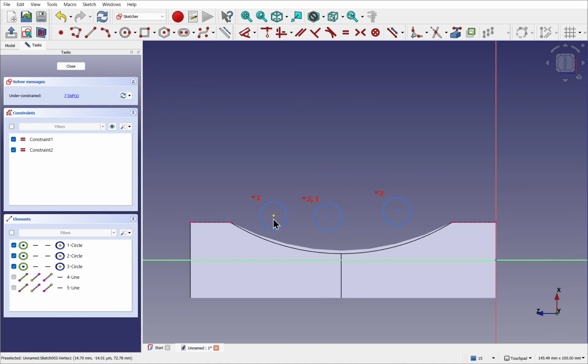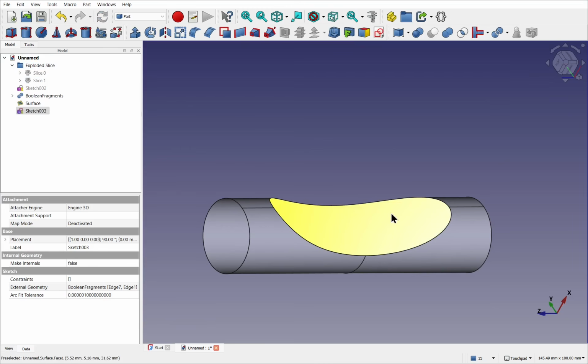Right click to cancel and then take these 2 points and the third one and put a horizontal constraint across those. Those are in line now. And let's make these 2 points and then the last point, use symmetry, and now we have our helper objects. Now I'm going to use these, put them in place to make the finger swirls. This won't show up if I close out. You can see you've got no geometry showing because those are construction geometry.